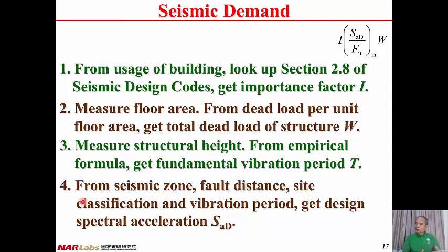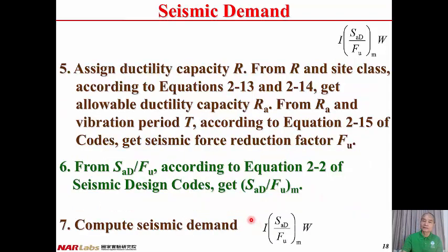And then we move to step 4, from seismic zone, fault distance, site classification, and vibration period T. And then we can have the design spectral acceleration SaD here. Therefore, the structural vibration period is necessary for the calculation of the spectral acceleration SaD.